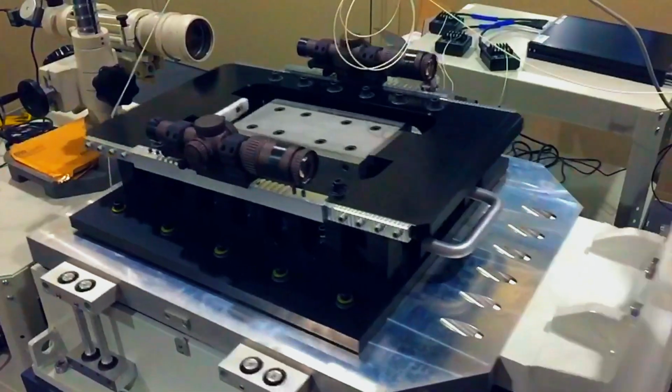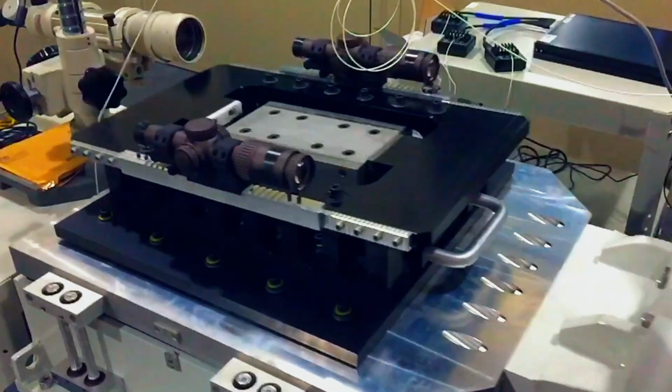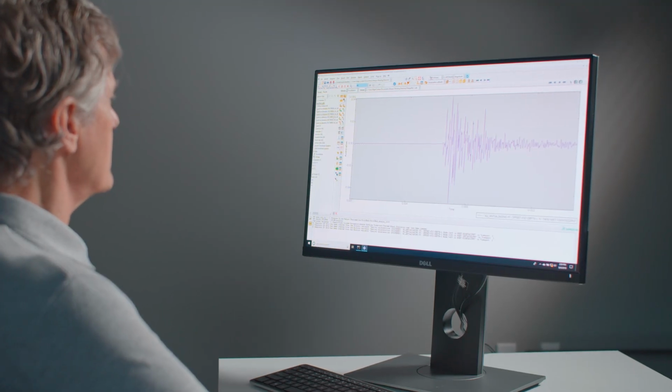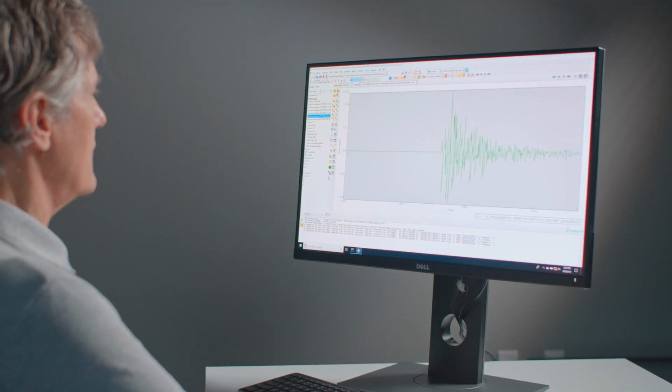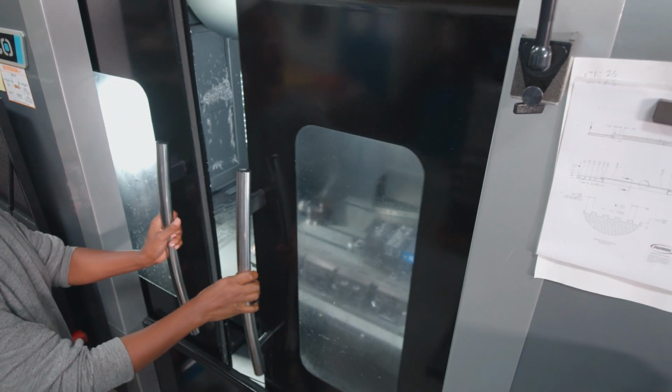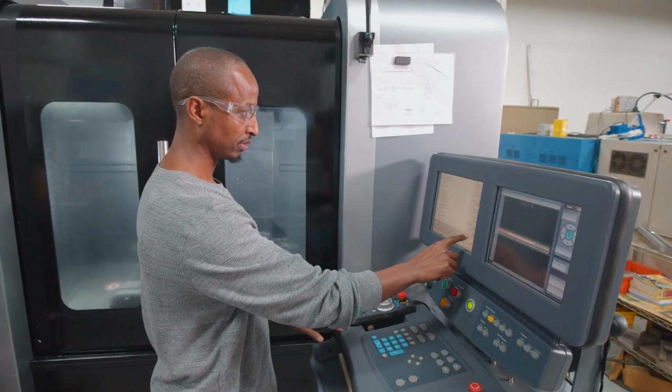Once I'm happy with the simulation, I can use FE-Safe to ensure the product has a good fatigue life. When the shock occurs, there's a lot of strain cycles that occur, and these strain cycles can cause a lot of damage. FE-Safe will pinpoint the critical locations and help me to identify areas of the design that have weaknesses and may fail early.